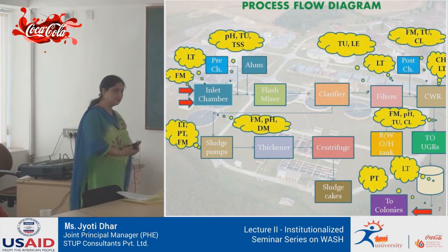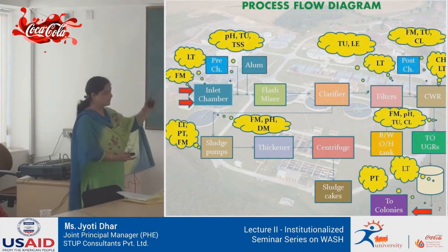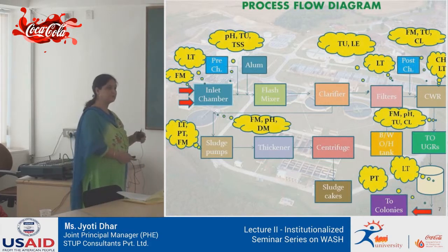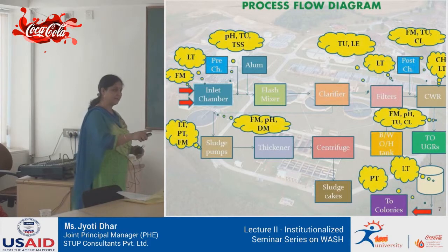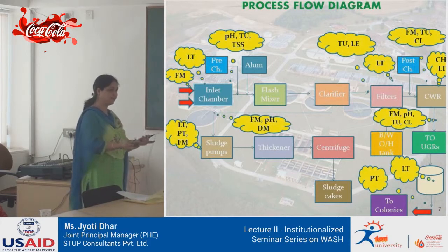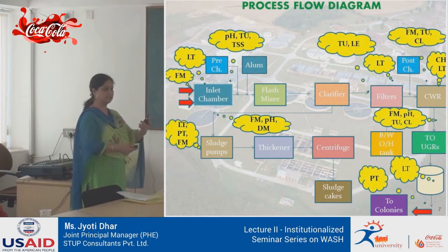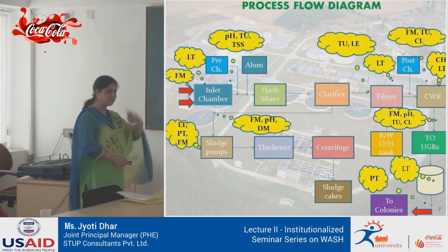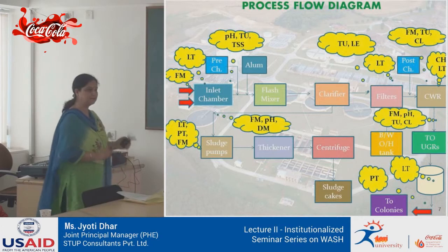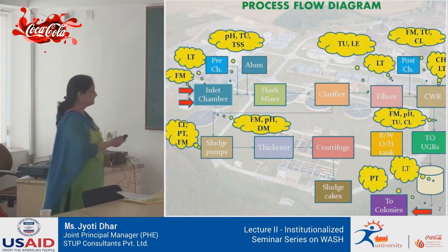You have ladder logic, sequential logic, and functional block diagrams. All these programs are fed into the SCADA, and then you give a set point for that. Once you know the height of the tank, suppose it's 5 meters, then you set the set point so that at 2 or 3 meters it should start, and at 6 meters it should stop. You feed the program in the SCADA for that.